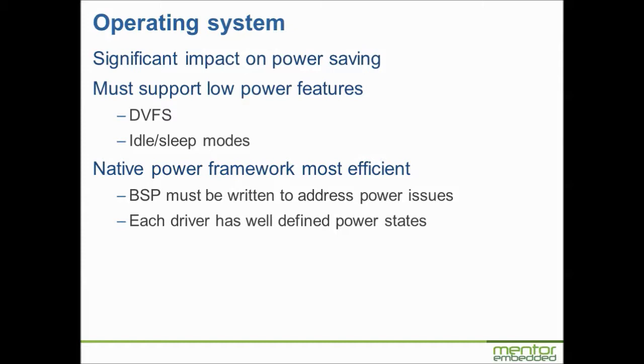So BSPs, the board support package, must be written to address the power issues, because that's the bit which is close to the hardware. Every single driver must have well-defined power states, because we know what different hardware can do. Maybe, for example, a given piece of hardware may be quite stable to be turned on or off, but it may only work at a particular frequency. On the other hand, a piece of hardware may be very relaxed about what frequency the CPU is running at in terms of its stable functionality. So we need to know how a given piece of hardware will respond, and that in turn, from the software perspective, gives us an idea of what each driver can do.